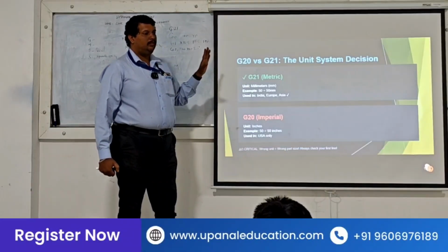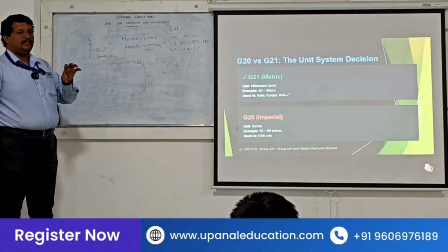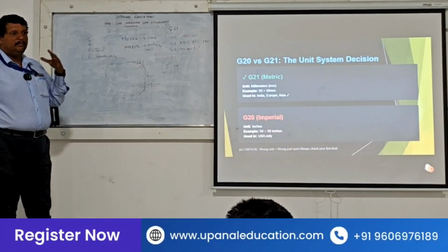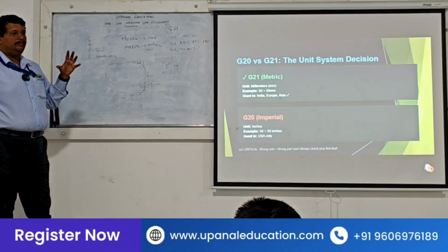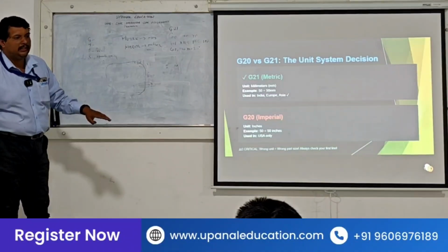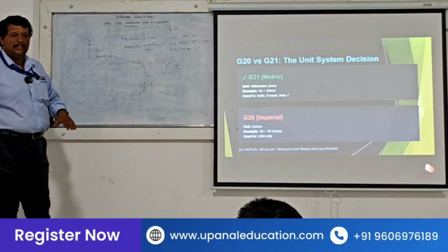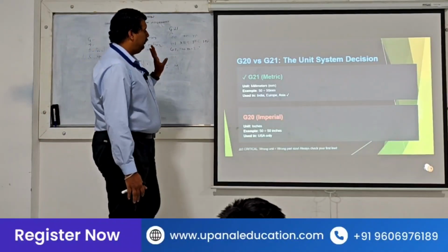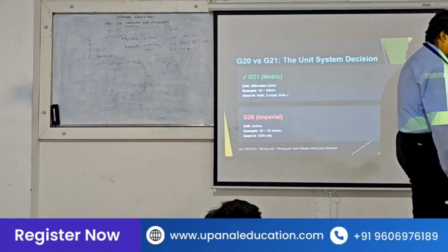Sometimes in the exam you may get confused. So remember: I comes first, so 20 is inches or imperial. M comes after that, so 21 is metric or millimeter. Understood? Any doubt, any confusion?